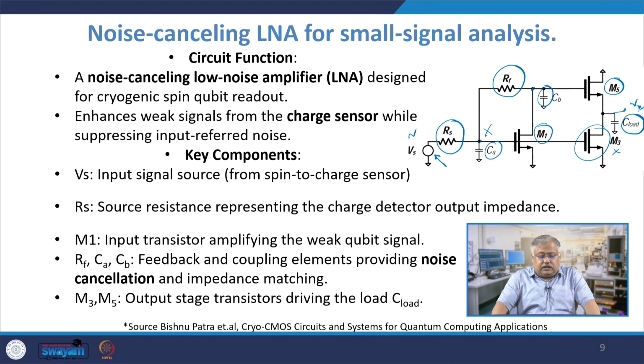Now, this noise cancelling low noise amplifier is designed for spin qubit readout, and it enhances weak signals from the charge sensor while suppressing the input referred noise. All your input referred noise almost goes to 0 in that case.